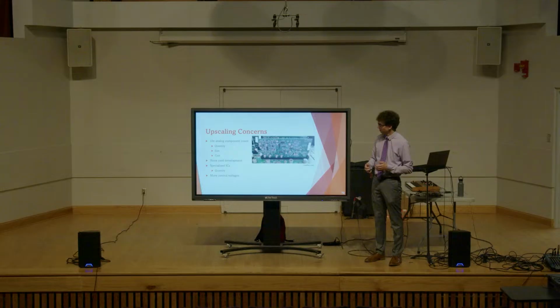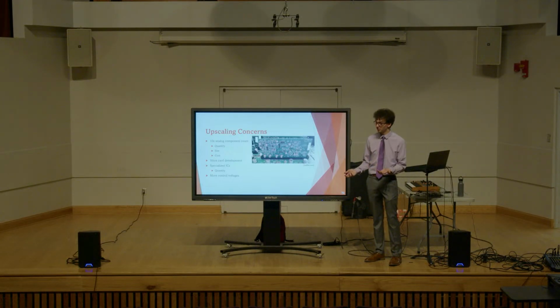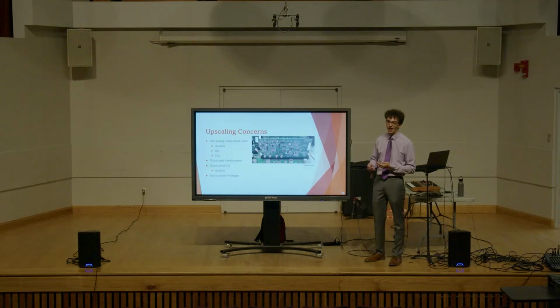And so a process that a lot of synth manufacturers have come to use in the last several decades is developing voice cards, which are compact individual cards for a voice that include all the circuits for one voice, and you make as many of them as you need voices. And then you have a master control board which will receive X number of these voice cards. When I end up making this into a polysynth, I expect that I will be developing voice cards and also using specialized ICs, which I've been avoiding for now for the sake of learning.